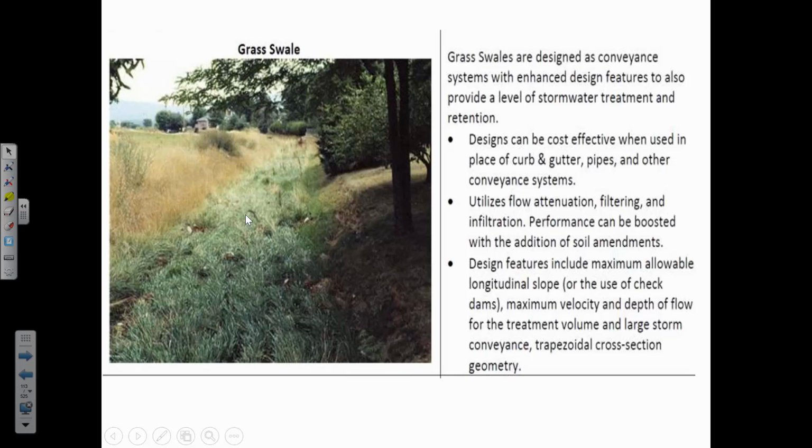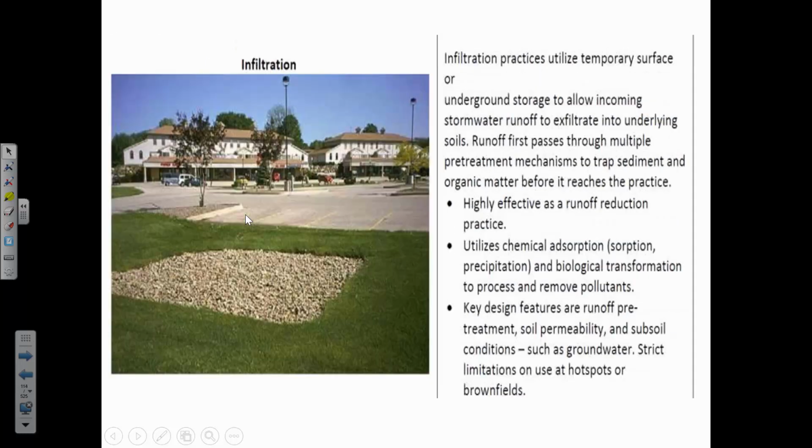But anything we can do to slow down the movement of water and delay it inside of the watershed is going to reduce the peak that has to be accommodated downstream. And so when water moves quickly and it all pools to a single place at a single time, that's when damage occurs. But if we can just delay it at every step along the path, then that's going to decrease the height of the runoff hydrograph.